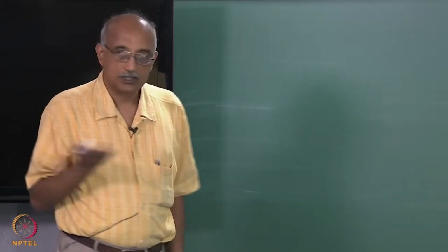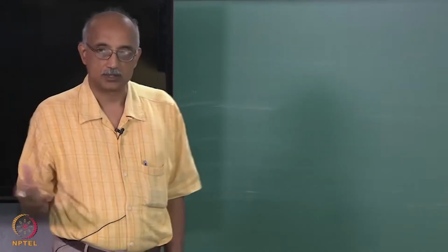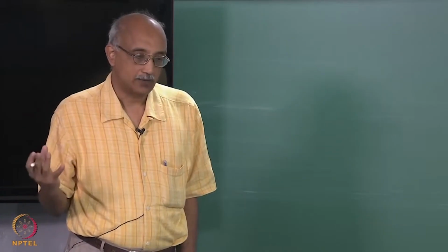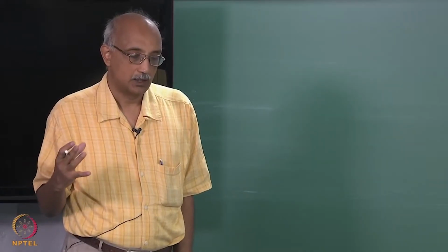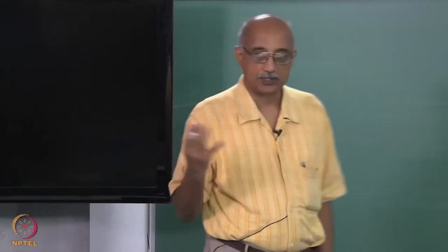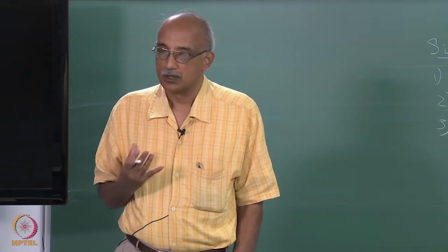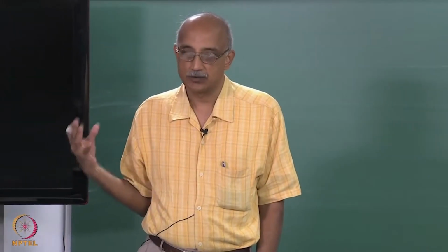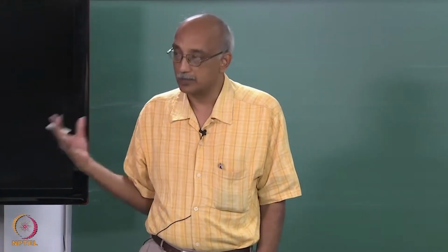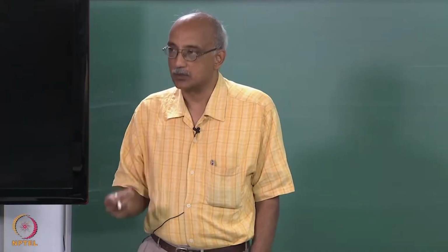So, if you look at silicon CVD, how would you describe the chemical reactions? We have said before that in a CVD reactor the best way to model the homogeneous rate processes is by using a free energy minimization approach, right. But that assumes that you are driving every process to equilibrium, and it also assumes that you have absolutely no insight into the processes that are going on.